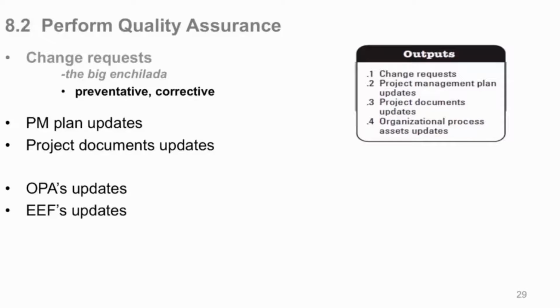Remember the control charts where you're measuring, let's say you need to build a number of things, and today, here's your baseline. It's right on the baseline. Here's a little up, here's a little down. Okay, well, you have your upper and lower control limits. Once it goes beyond an upper or beyond a lower, that's a real red flag. And if you see that coming, and with control charts, it may be more difficult to see, but sometimes you see the things going like this, and pretty soon they're going to hit this. You need to do something to prevent that from happening.